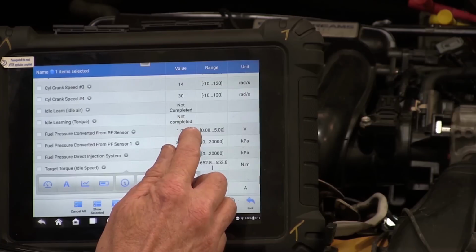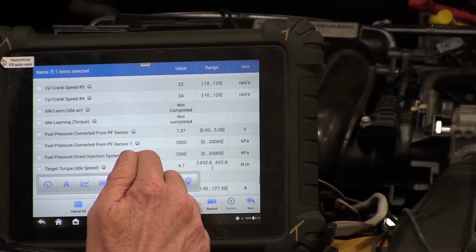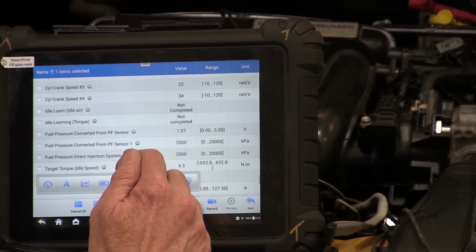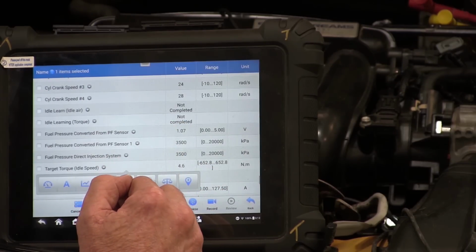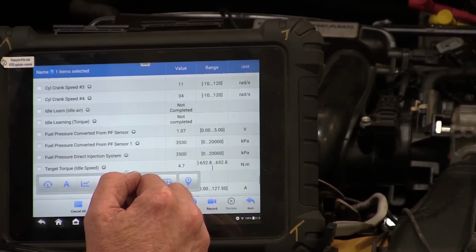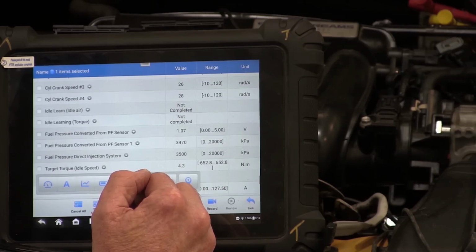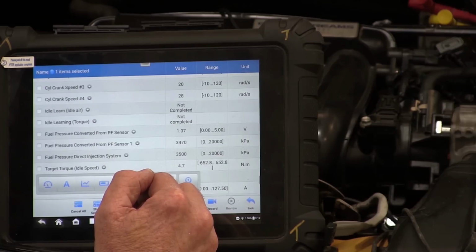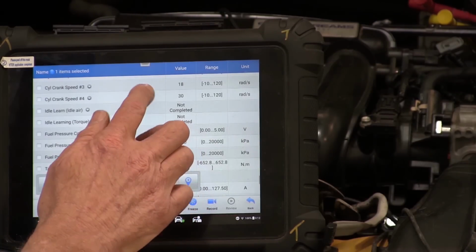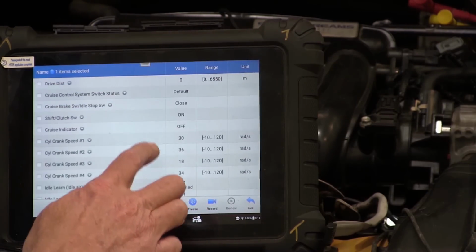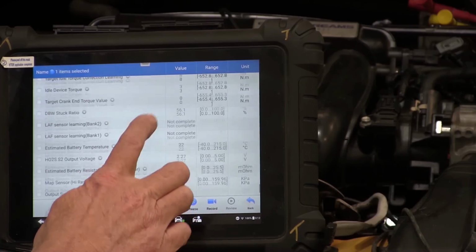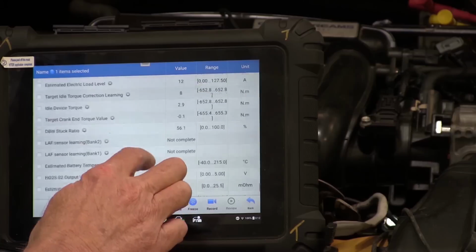And it seems like I'm overdriving the duty cycle, and I don't see any duty cycle in this list either for driving the high pressure pump. But I'm not going to go down that rabbit hole right now, not when I can see that kind of injection on time. The injection on time on this, at a millisecond or so, is too much for a GDI engine at 500 pounds of pressure. So I don't think I want to go that way.